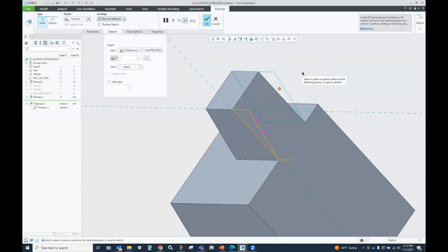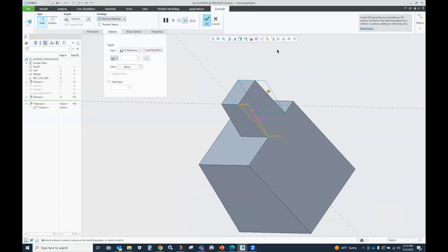And although through all would have worked, it causes Creo to work a little bit harder, because through all says look throughout the entire model's bounding box for anything else that it might intersect and then create the feature. Now, if that's truly what you wanted, then that's what you would do. Maybe there's another one of these protrusions down over here that you want to pass through.